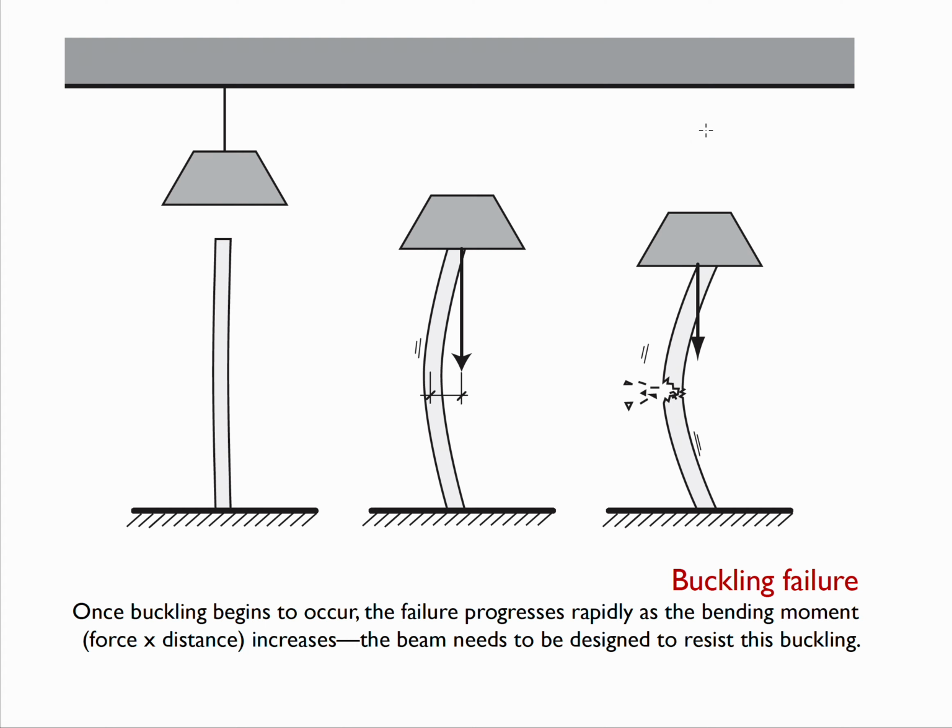So recognizing that the primary consideration of columns, that resisting the forces that come down, is actually relatively easy. It's resisting buckling that's difficult, and it's also difficult to predict. And the reason it's difficult to predict is that once failure in buckling starts happening, it can be catastrophic.